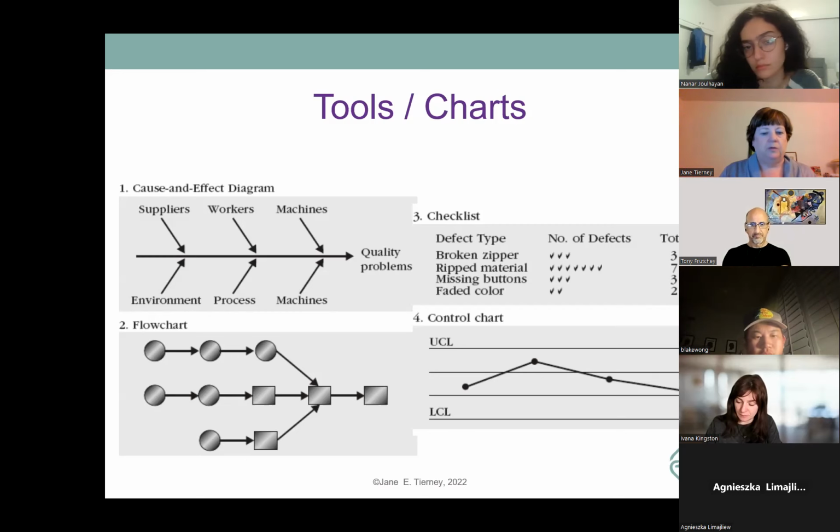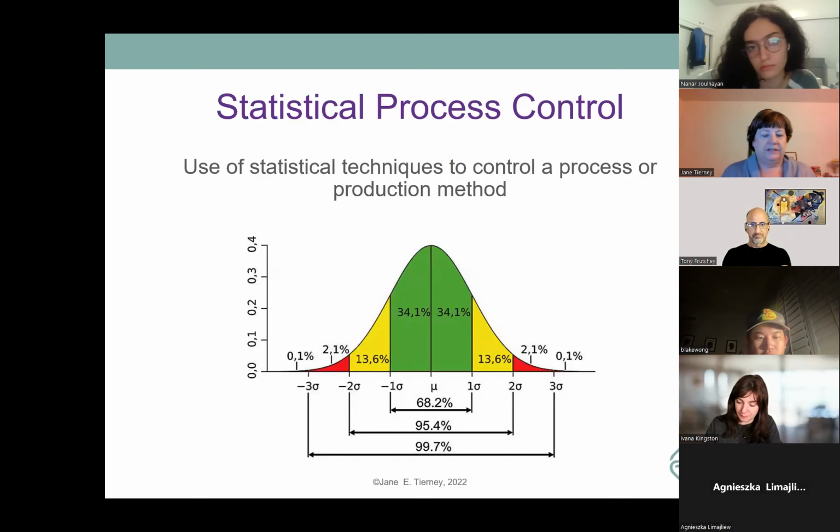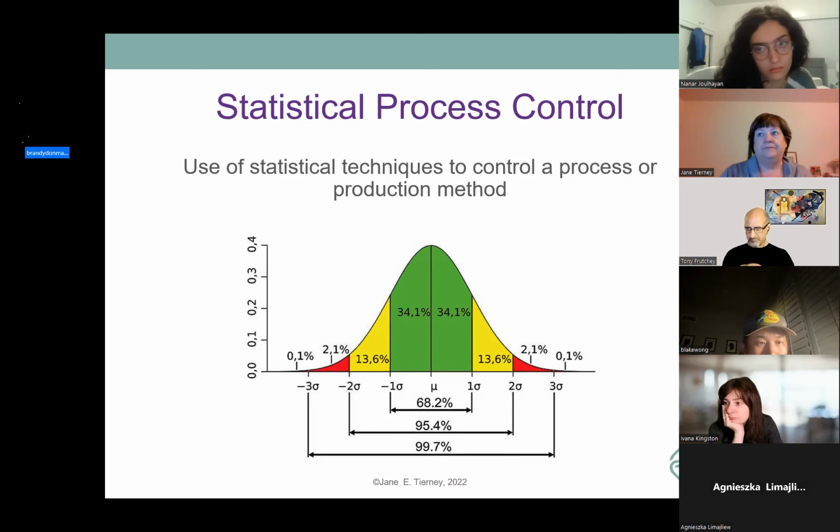And then the control chart we looked at, these are the things that we actually graph over time. Here's the statistical process control chart, again, with the 99.7% with the 3 sigmas on each side of the mean. And then if we get out to the 6 sigma, we're at the 3.4 opportunities per million, which is a good number to put on the test, right? What is 6 sigma equal in terms of defects? And then give you some change.